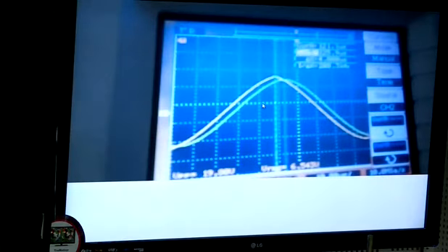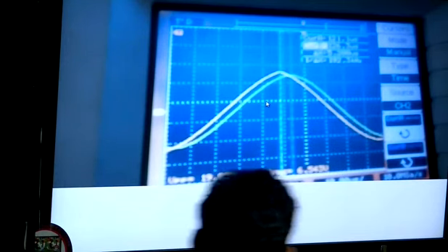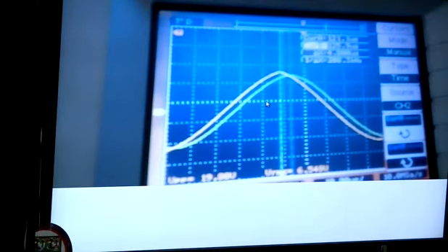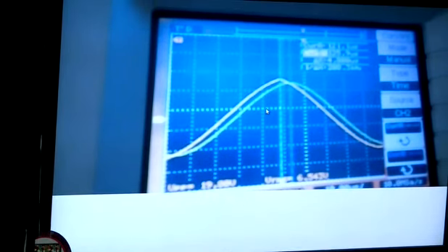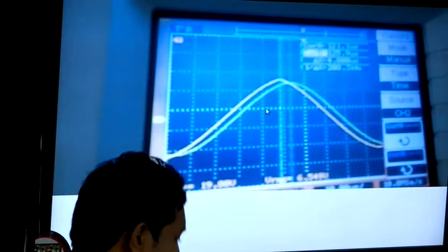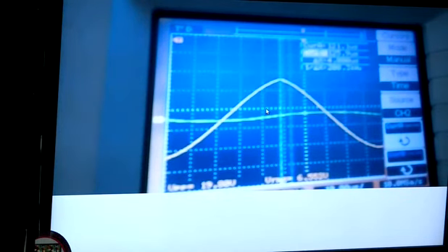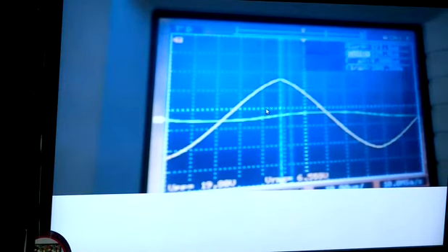If I switch over to another camera, here we are trying to measure the time difference. Since it is difficult to directly see and do it, the way it is done is there will be some guidelines. You can just adjust it, and then it will show how much is the difference. So how much is the difference? 4.8 microseconds we are getting, which is almost within the limit.